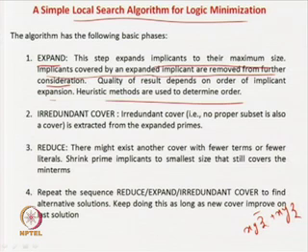If you have a function of x, y, z, you have to represent all the min terms, that is, after expanding all the terms of the SOP in terms of all the literals. But here you select one of them and you expand fully. Then with the maximum size, implicants covered by expanded implicants are removed from further consideration. Obviously, if you have an implicant which is covered by some other, you can eliminate it. Now, the results will depend on the order of implicant expansion, like whether you should start with x or y or z or a or b or whatever.